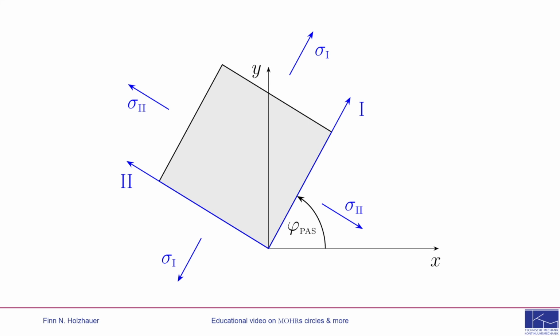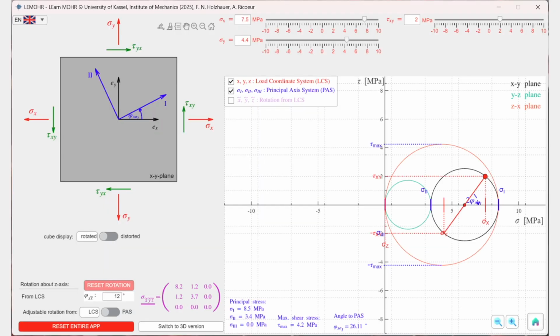The direction of rotation is reversed compared to Mohr circles. A rotation about the 3 axis in the mathematically positive sense, here counterclockwise, corresponds to a clockwise rotation in Mohr's circle, and by a factor of 2. This factor of 2 arises from the coordinate transformation relations.